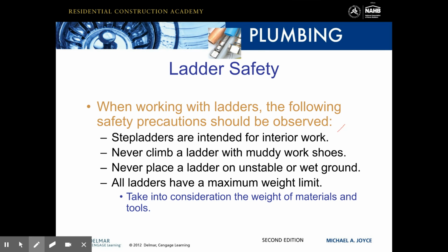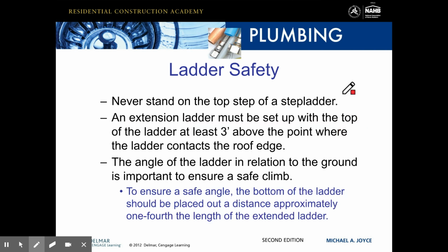It's important to note for your step ladders, the most common sizes are 6 feet and 8 feet. Never stand on the top step of a stepladder. They all say it, so don't do it.